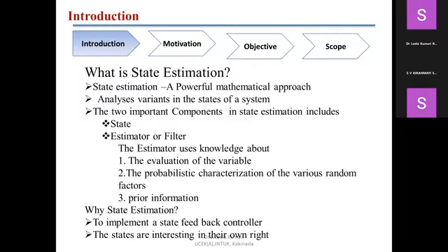The modeling and performance analysis. Performance analysis is completely based on the simulation results of various nonlinear estimators. It is carried out here: system models of various nonlinear estimators, applications of these estimators for different real-time applications, and their performance analysis in terms of speed of convergence, error performance, and all these things. And the state estimator concerns the problem of estimating the probability density function for the state of a process which is not directly observable. So this involves both predicting the next state and applying corrections based on the measurement equations.